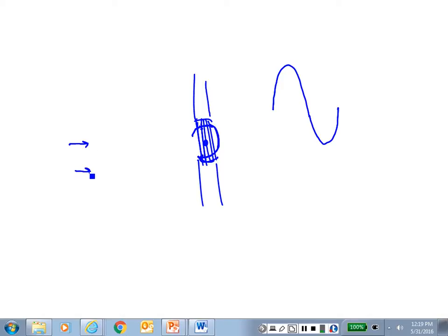So here's my output. And my switch would look like this. So when this was a positive and this was a negative, I would have this. It would be a two position switch. But I would put this up here. When this changed polarities, this went positive, then I would switch that down like that. Right? You understand? Well, then what I would always get is I'd always get positive. I would get this guy right here. But I would have to switch it in sync with the generator. Well, good gracious, the generator's in motion. Why can't we let the generator switch it for us?